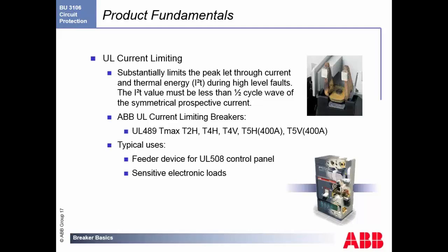Using breakers in the right way with the right settings for the trip curves, and if you do selective coordination, which is using the right breakers down the stream, you can reduce the amount of damage, the amount of downtime, and the amount of maintenance that is required on your equipment. Plus, you're also getting a much higher level of safety for all the people involved in maintaining that equipment.